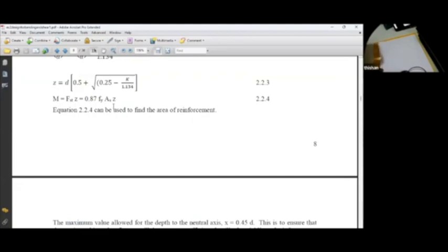Otherwise, how could you say the reinforcement requirement in a beam having a depth of 600, width of 300, span of 6 meters, is 3 numbers of 20 millimeter bars? And a young engineer would quickly check it on his computer program, Excel sheet, and he confirms, okay, this engineer is correct. Yeah, her answer is correct.